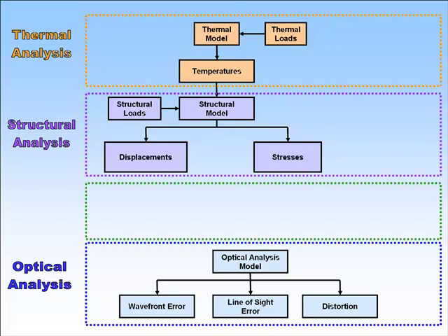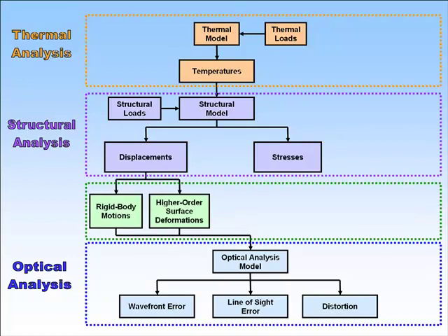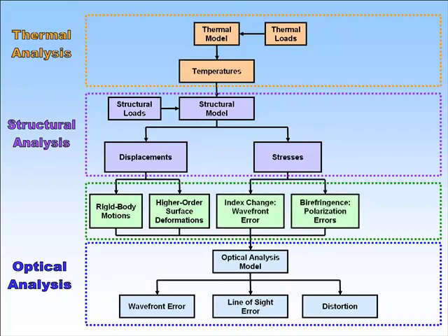The link that facilitates bringing these disciplines together takes the displacement predictions from the structural analysis and describes them in terms of rigid body motions and higher order surface deformations in forms that can be imported into the optical analysis model. Likewise, the stress predictions in the transmissive optics from the structural analysis may be converted into refractive index and birefringence changes due to the stress optic and stress-induced birefringence effects for import into the same optical analysis model.